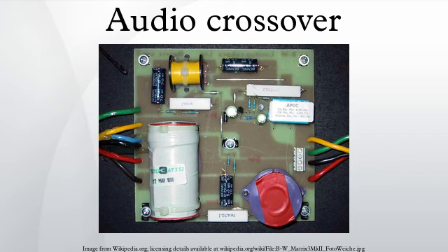For active crossovers the high-pass filter's output is inverted. In three-way systems the mid-range driver or filter is inverted. However, this is generally only true when the speakers have a wide response overlap and the acoustic centers are physically aligned.